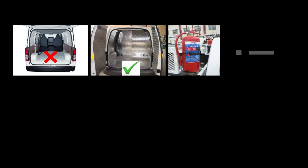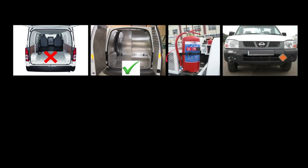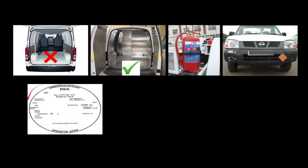Here are your quick release brackets. Here is your DCP fire extinguisher, and there are 2 of them, as we can see. Here are the 600 millimeter or 60 centimeter rails on the side, as this is an open vehicle. Here is your dangerous goods warning diamond. Remember, this must be on the front of all dangerous goods vehicles. And remember, when you offload the dangerous goods, you turn this around to indicate that there are no more dangerous goods in the vehicle. Here is the operator card, and it shows category D.